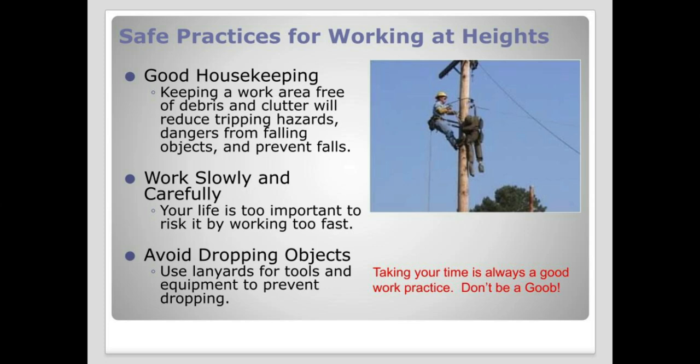Safe practices for work: good housekeeping. Keeping a work area free of debris and clutter will reduce tripping hazards, dangers from falling objects, and prevent falls. Work slowly and carefully. Your life is too important to risk it by working too fast. Avoid dropping objects. Use lanyards for tools and equipment to prevent dropping. Taking your time is always a good work practice.